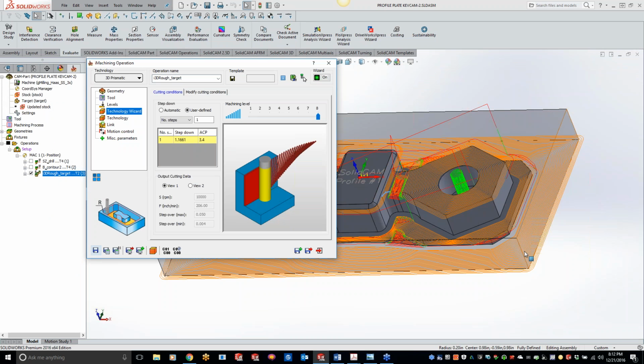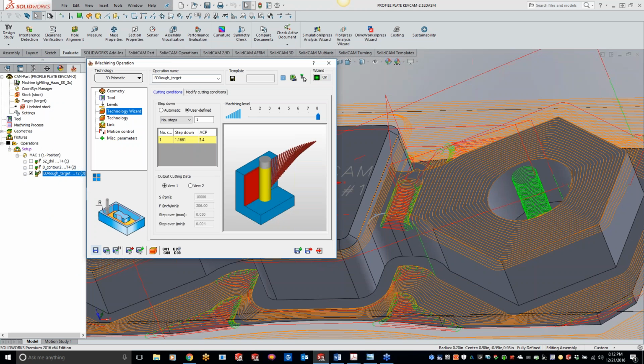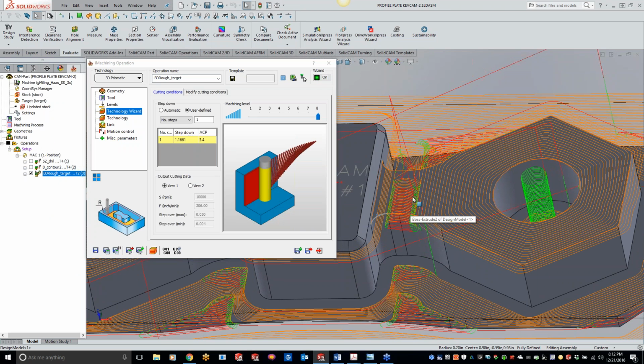So now, like I said, I need to have a visual appearance on this. It needs to look pretty. If you see, like right here, when we're doing the D-slot trochoidal with that separation channel right there, we have a lot of the D-slot trochoidal movements. So you're not going to get the prettiest looking finish on there. If it's an internal part no one's ever going to see, it's definitely going to meet specs by all means. So it wouldn't matter there. But like I said, we want to make it look pretty.